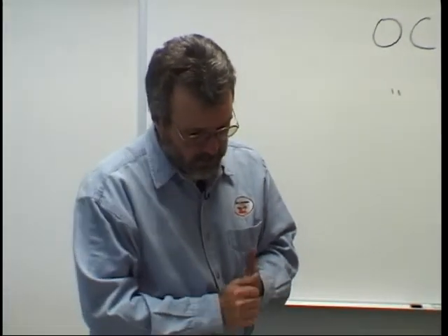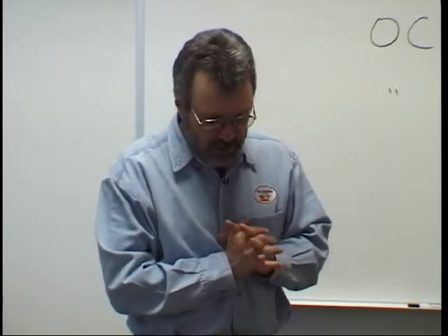Flip the page. On page 784, there's a bullet at the bottom of the first column. The shielding gas or gas mixture is an essential variable for most welding procedures. I've talked about essential variables before. I want you to understand, I may ask that question. I may ask you to name an essential variable associated with this. So that's the question, the answer I would want.